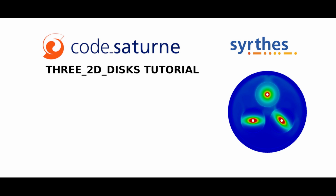The aim of this tutorial is to simulate the natural convection flow of air inside a sheath containing 3 electric wires. A 2D cross-section of the sheath is considered. Thermal conduction inside the 3 wires is solved with SYRTHES and coupled with the flow solved with Code_Saturne. In the first 2 steps, uncoupled solid and fluid calculations will be set and run separately. Then, a coupled solid fluid computation will be solved.